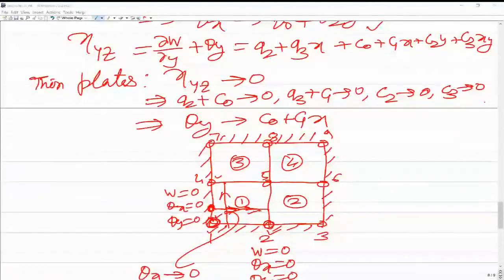Yeah, but for thin plates, definitely the classical plate bending elements are better compared to shear deformable plate bending elements. But where we don't know, we want to use an element which predicts the results for both cases. So in other words, for thick plate, we can use first order shear deformation theory. Yeah, for thick plate, you can use first order shear deformation theory. For thin plates, you can use classical plate theory, but I am saying where you can't identify.